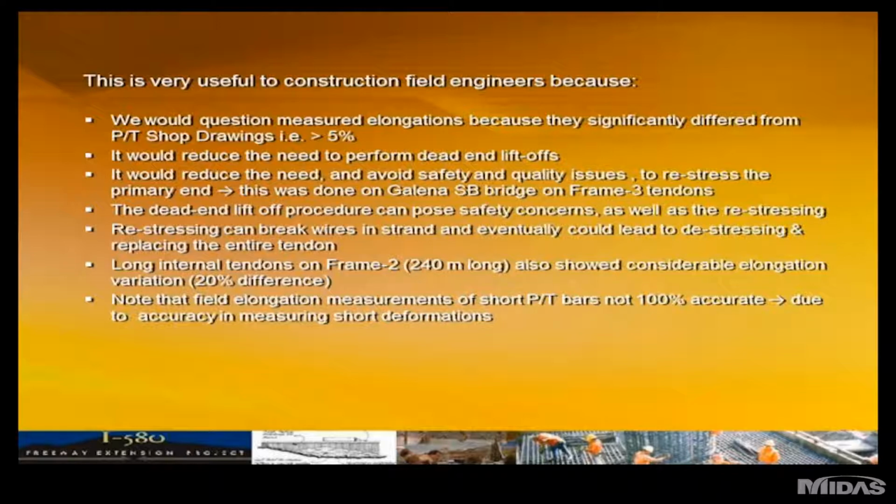If he doesn't, then we end up doing dead-end liftoffs. We may end up, if we do dead-end liftoffs, which is a very dangerous item, there's a chance that you can break strands or wires. There's a huge safety issue. We ended up doing this on the southbound bridge frame 3, and we ended up breaking some wires.